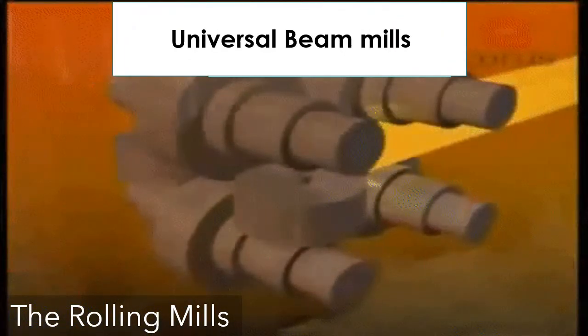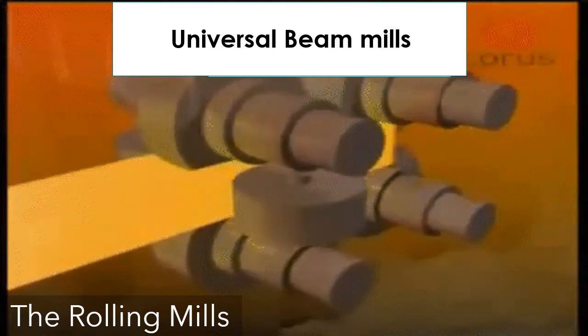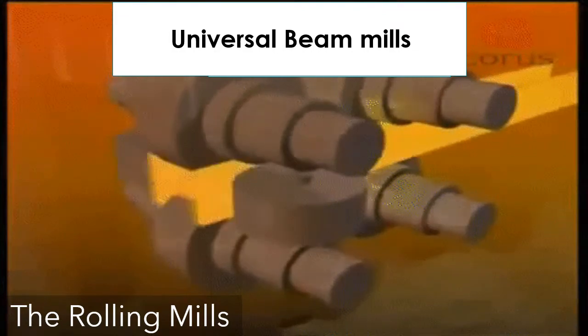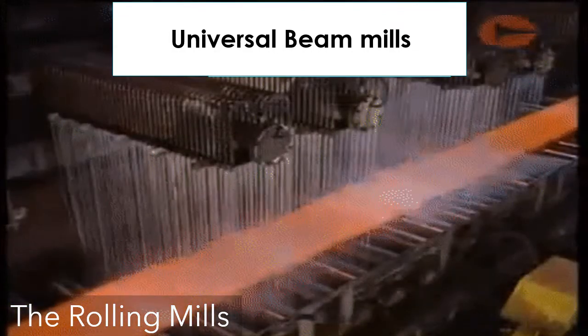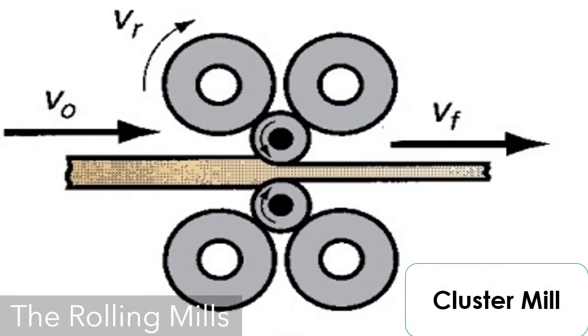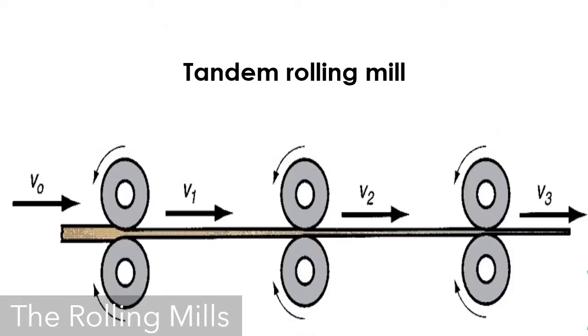The universal beam mill includes stands with both horizontal and vertical rollers acting on the steel at the same time. The rolled steel after that is cooled. The other types are the cluster mill, with multiple backing rolls on small rollers, and tandem rolling mills, where a sequence of two-high mills operate on the part.